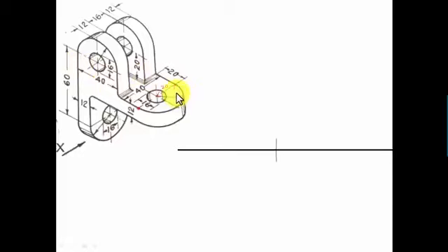So the maximum width of the rectangle we're going to draw is 80. Now for the height: all these semicircular profiles that you see have a radius of 20 millimeters, since all of them are congruent to each other. From this center to this center, the distance is 60 millimeters, and if we go upstairs, this distance works out as 20.